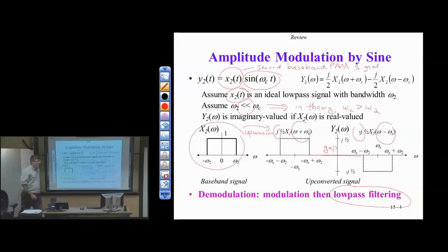Well, we already know it's tuned. We know from the previous slide it's tuned to the pulse shape, or something about the symbol rate. But again, we got 3 filters. It turns out we have at least 2 filters here in the receive side. We've got the modulation low-pass filter, and we have a match filter, which is also low-pass. So why have 2 low-pass filters when one will do just fine?